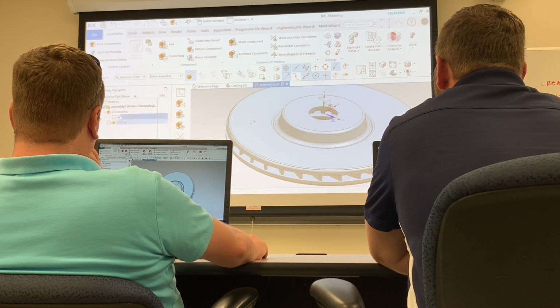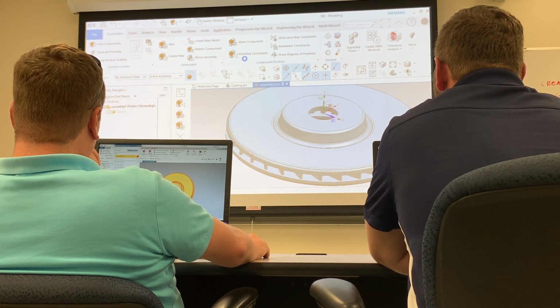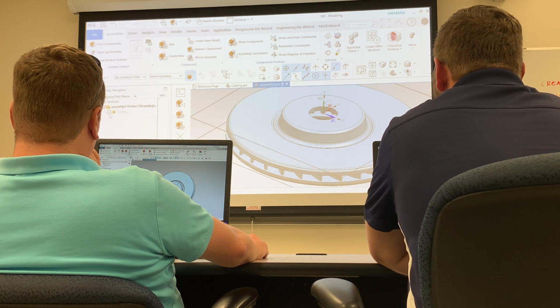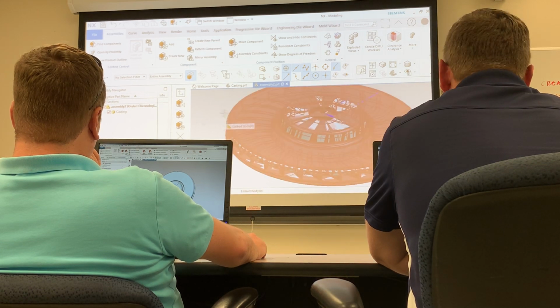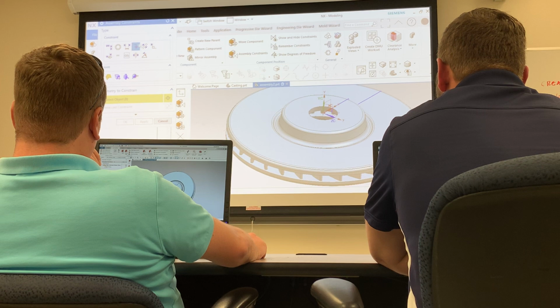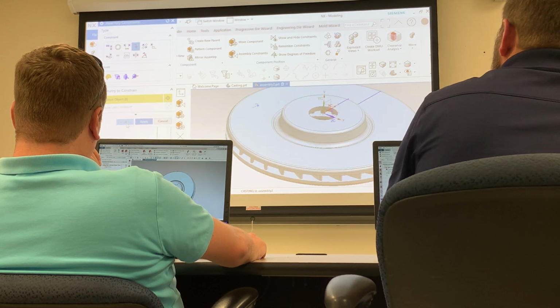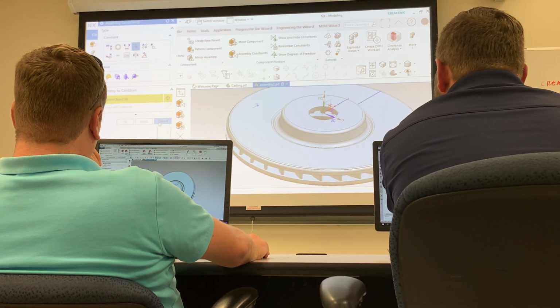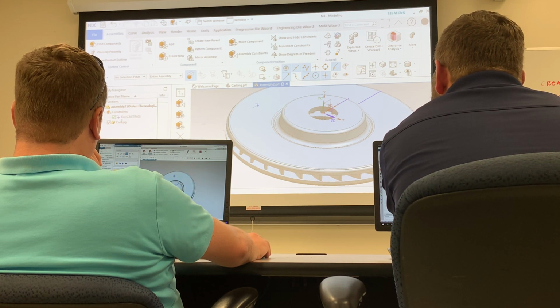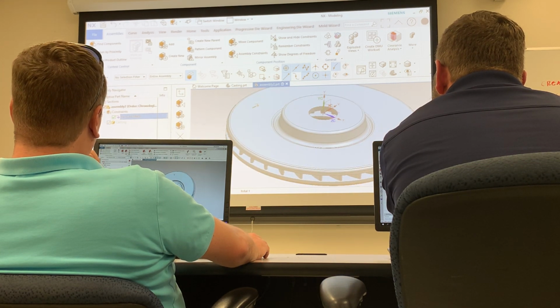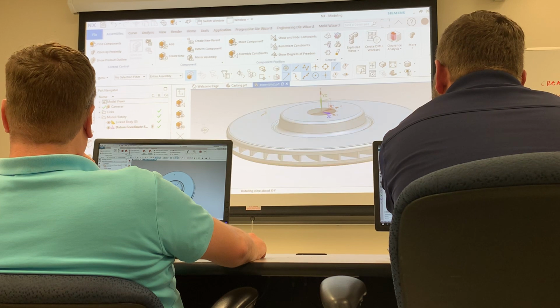All right, so I'm going to delete this off of here. Alright, so you're under assembly constraint. Do you have the casting enabled? I mean, is it visible? No. Does it need to be? Yes. Okay. Yeah, assembly constraints, and then apply that fixed constraint. So apply and then cancel, and you should be in here like that. Then just suppress that casting, and you'll be left with a complete body.